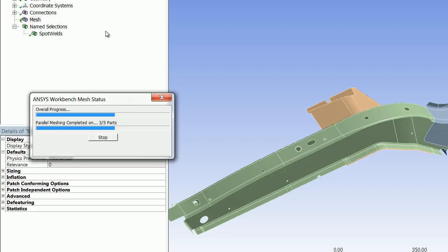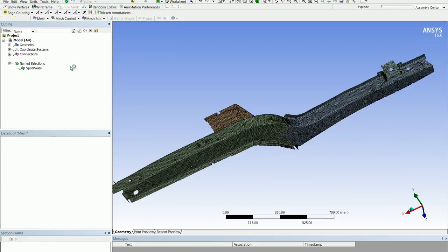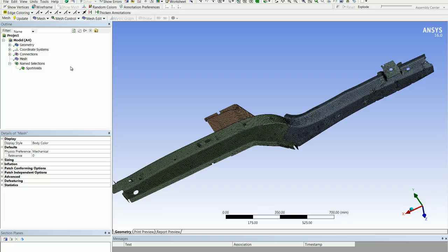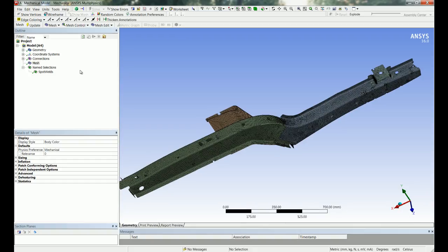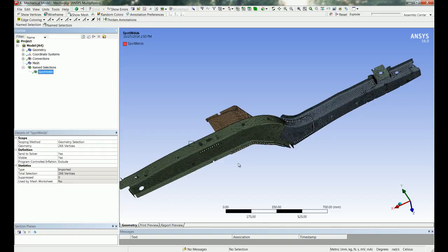In general, the mesher tries to get a high quality mesh automatically, but in some locations the trade-off between which features to capture and mesh quality can overconstrain the mesher. In these areas, the mesher will often err on the side of capturing the features. At times, a user will have certain quality metrics they want to achieve and want to improve the mesh so that no elements are below that criterion. This can be done by using custom legends and just fixing up elements that are displayed in red and/or yellow.